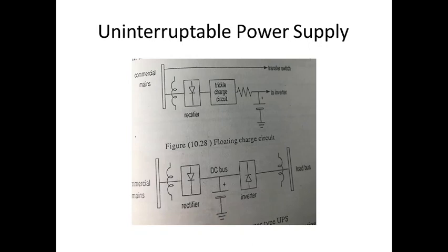The main advantage of this is that the battery is always there in the circuit. It is always powering the inverter, and no transfer switch is required. The design, cost, and life of the transfer switch is a main consideration, since this switch carries full load power. Also, in the rectifier inverter type, there is no required circuitry which detects an outage of the commercial mains. So the battery simply powers the inverter all the time, including times of power failure.